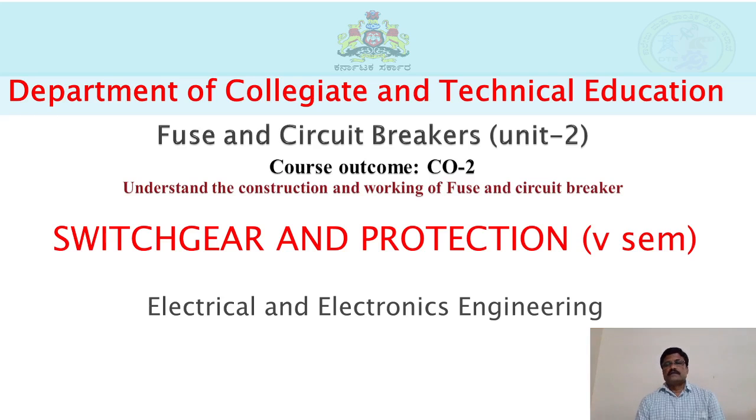Therefore, it is good practice to inspect the circuit breaker at regular intervals of 3 to 6 months. During the inspection of the breaker, the following points are to be kept in view.